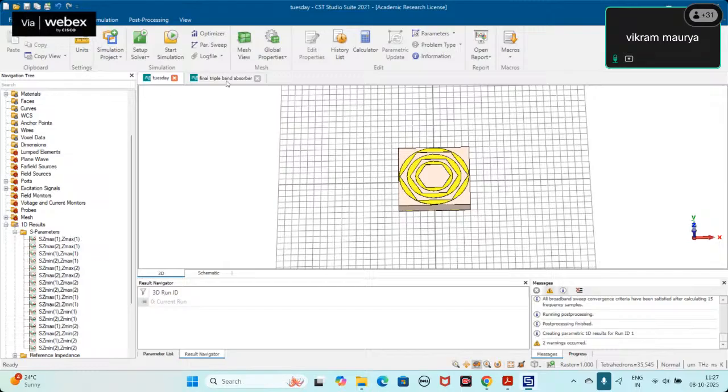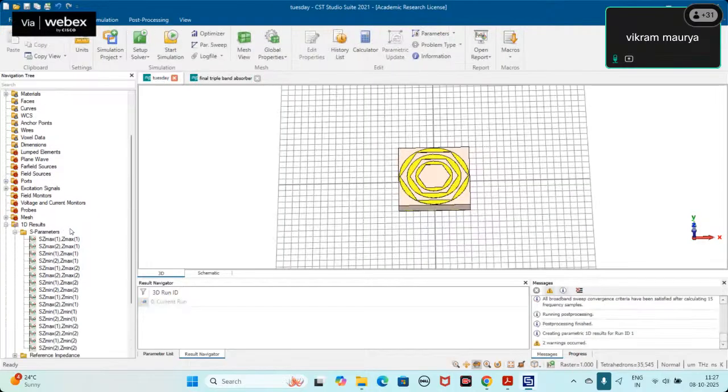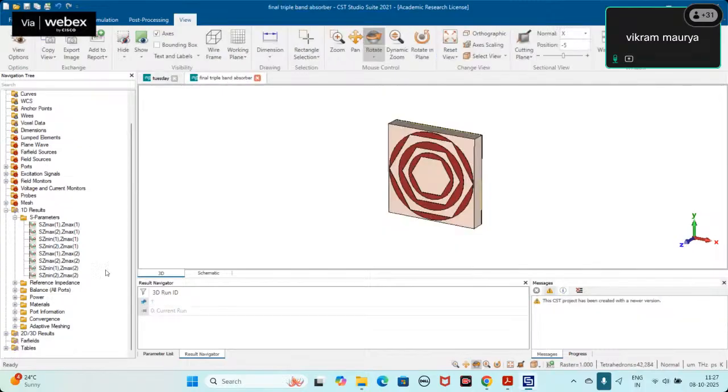See, in this case, in the S parameter, only this one result will come. But in this case, all the S parameter components will come. Why? Because we are choosing all the ports, not only the Zmax term. If I am choosing only Zmax, then in every case the signal is only incident from the Zmax side, from the front side only.